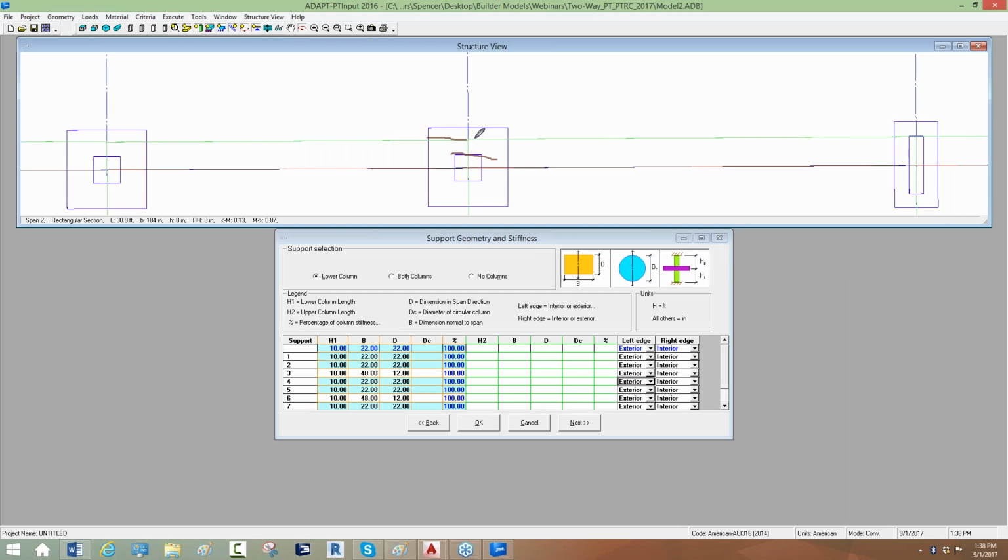Right there, there's our edge of slab. The program checks that distance. And if that distance is less than 4 times the slab thickness, it discounts this. It says this is a free edge along the face of the column, and now I have a critical section that is 3-sided, and this becomes an end edge condition rather than interior.